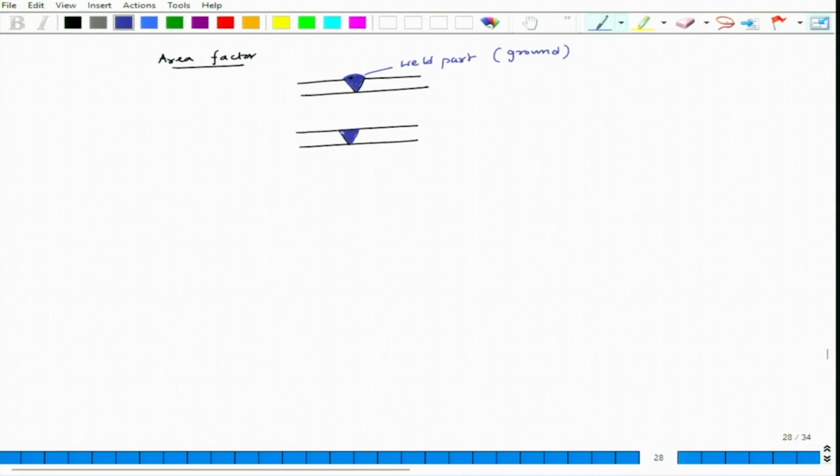Fine. And this is the modification. And now here this is the part which is to be welded. So here we have to make sure that this should be a noble weld material and this will be active. If it is the same, that's better, but if we don't find the same thing, then it should be active. So that here also, large anode, small cathode. So the corrosion effect of the active component would be less.